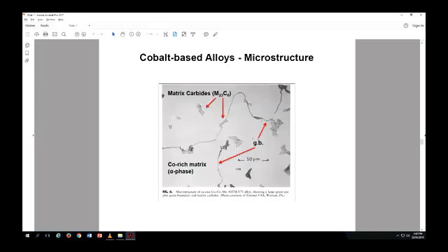But what it does is, if you look at this, this is what will happen. If you look under a microscope, these are the grain boundaries. You have a pretty large grain size, and then you have carbides. These are carbides that you have seen under the microscope. And you see that they're everywhere in the matrix, everywhere in the grain as well. That's going to give the material some weak points, which is not desired.